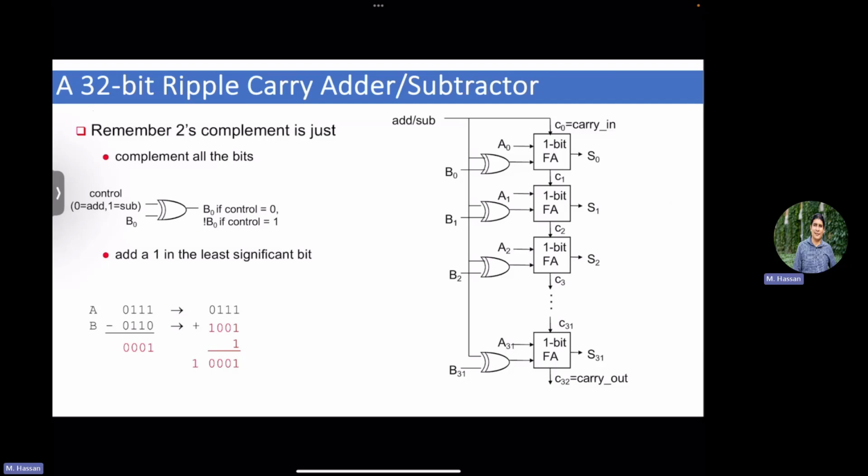For the 8-bit example, let's take a smaller number of bits, 3 bits by 3 bits. What is the maximum representation of a 3-bit? What is the maximum value? 7. Ignore the sign for now, so a value of 7. 7 plus 7 is what? 14. How many bits you need to represent 14? 4, right? So there is always one extra bit, because if you are adding 2 numbers of a certain width, the result can be double of each. So if you're adding 32-bit to a 32-bit, your result maximum needs 33 bits.